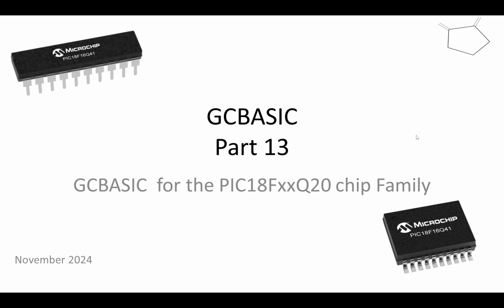What is SPI? SPI is an interface that's used between small devices on the microcontroller, such as a GLCD, shift register, sensors, or SD cards. They use a clock line. They use two data lines, a serial data out and a serial data in. They may also have a select line or chip select to help you choose from multiple devices that will be on this SPI bus. So your chip select, if it's high or low, the device will accept the commands.